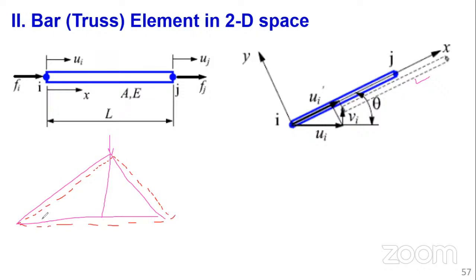So we are considering this deformed shape, and maybe now we are considering this node where there is no support. If there is a support, of course, we know the node here doesn't move. But we assume a point here, an arbitrary node where there is no support, such that we can have deformation in both x and y.